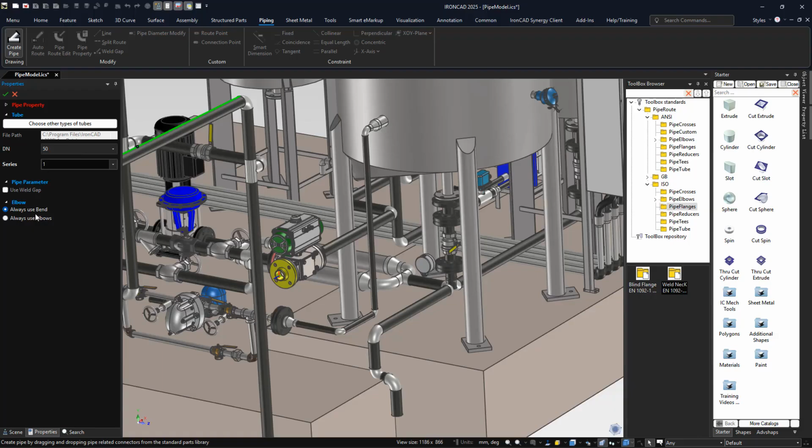And then you can add certain things like your bends and or your elbows. So if you want to use a bend that just creates a pipe using regular bend, like a sweep bend, if you will, you can use that. Or if you have elbows, you can select that, and you can also choose that. By default, it'll go to the 90 for the particular standard that you started with, which is in our case ISO. So it's going to use the 90s for the ISO, which we'll use as our standard. So we'll go ahead and hit OK to apply that.